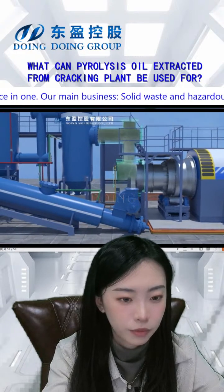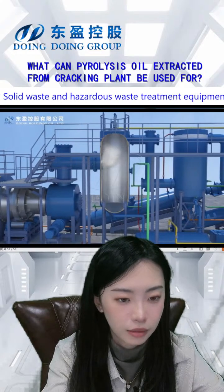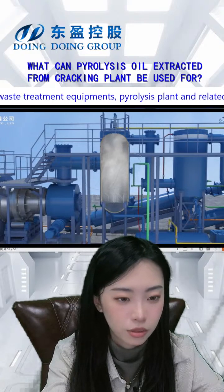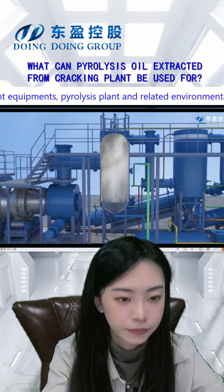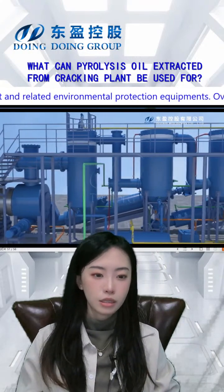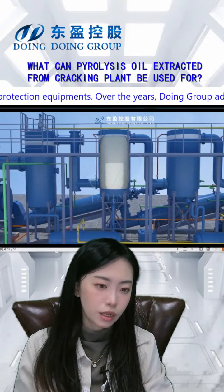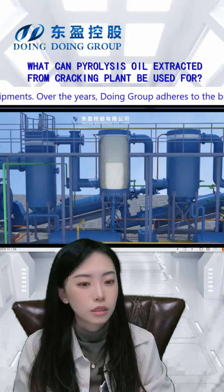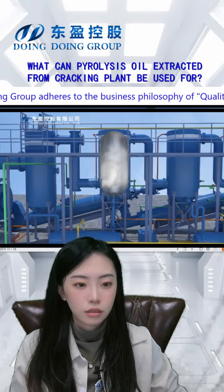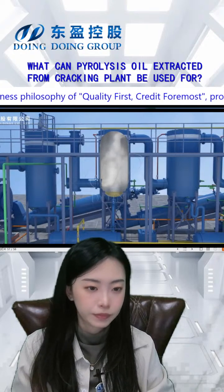And then let's talk about the flue gas, how to condense it. First, we come to the buffer tank to slow down the speed of the gas and to settle down the carbon black. And then here are 3 cooling buffer tanks, which also slow down the speed and purify the carbon black. Outside is also a circulating water cover to condense it.